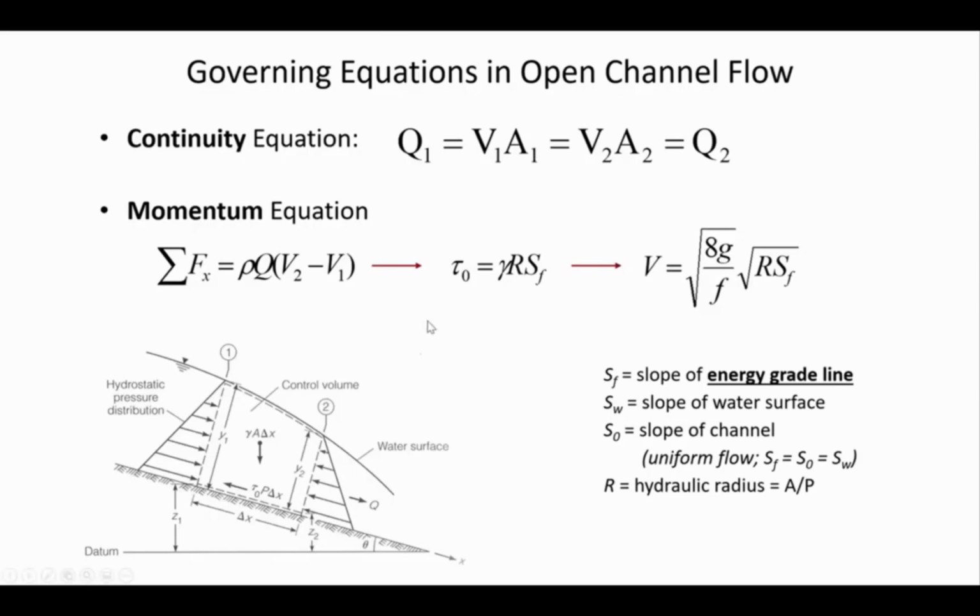Okay, so continuity will be one of the tools we use this semester, and then the other is different equations that are derived from the momentum equation. And so in the momentum equation, what we're doing is we're looking at the imbalanced forces. And since we have a difference in velocity between the flow in and the flow out of the control volume, the momentum equation can be rearranged to allow us to calculate the magnitude of the shear stress that's applied.